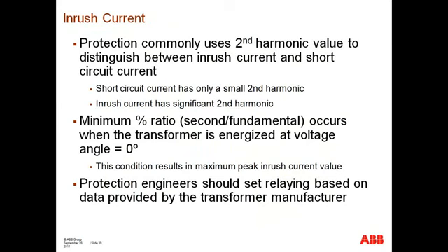Okay? And these are some of the fundamentals. The bottom line is that, from a best practice perspective, second harmonic inrush settings used to identify that inrush occurs really vary from 8% to 15%, and it's pretty important to consult the manufacturer of the transformer, since for the most part it's a function of some random components, such as the point on wave at which the voltage closes, but it's also a function of the manufacturing characteristics of the transformer. So anywhere between 8 and 15% is reasonable.